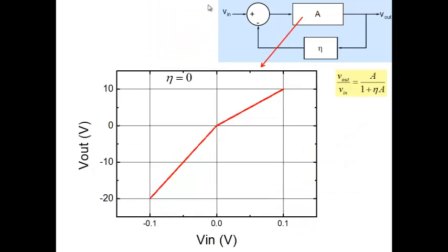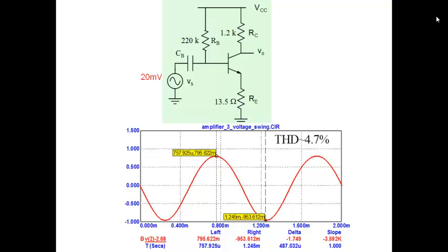So coming back, putting a negative feedback, yes, it attenuates. I get 10 millivolt here and 10 millivolt here. Fine, that's a simple voltage divider. But in addition to that, the distortion is not proportional to the 10 millivolt appearing here. The distortion is not 10%, the distortion is 5%, because negative feedback is helping to linearize the amplifier and you get a lesser distortion.